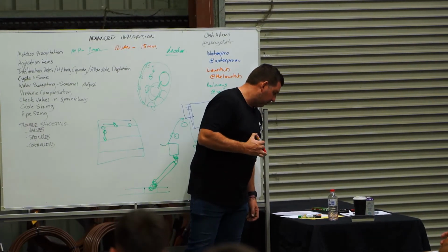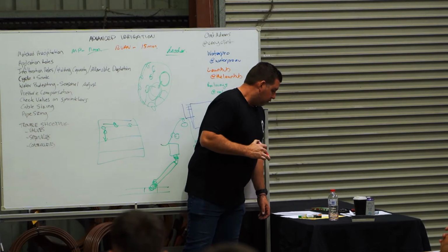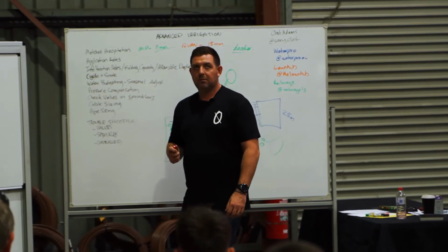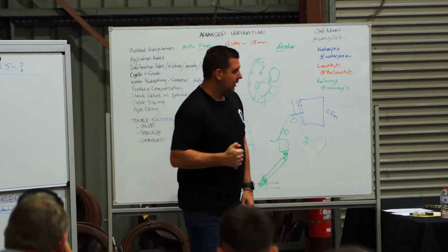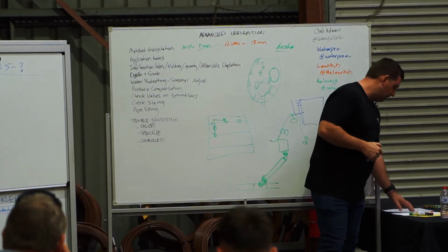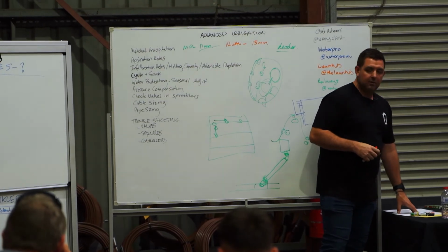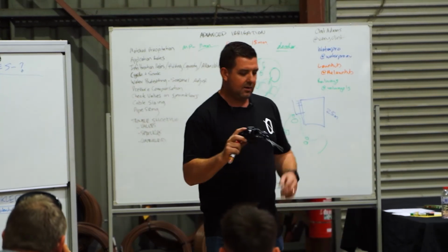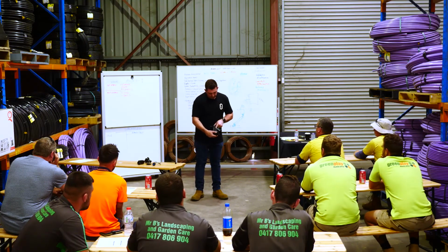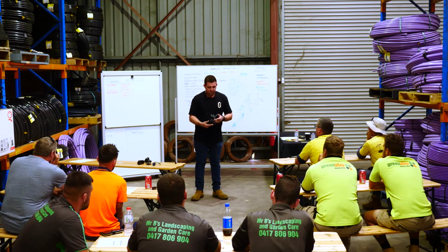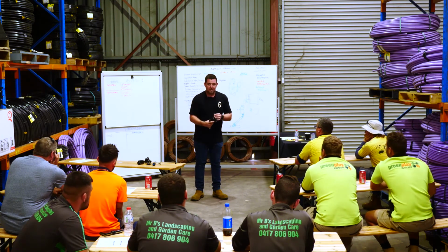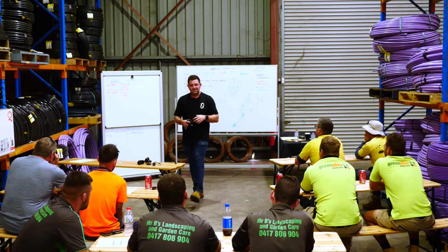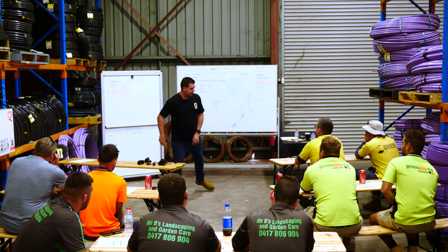What else can happen with a solenoid valve? The only other two things that you might find with a valve is that it's chattering, or that it's vibrating. You can use the flow control to adjust the amount of water that's coming through. You might be getting water hammer through the valve. That top thing there is the flow control. It's not something that most people touch. You can't adjust the amount of pressure that comes through a valve using the flow control, but you can push down on it and it might fix the hammer. I wouldn't be playing with it too much.